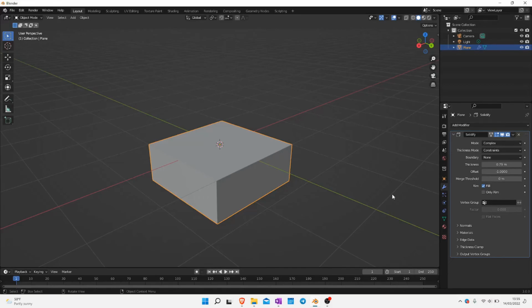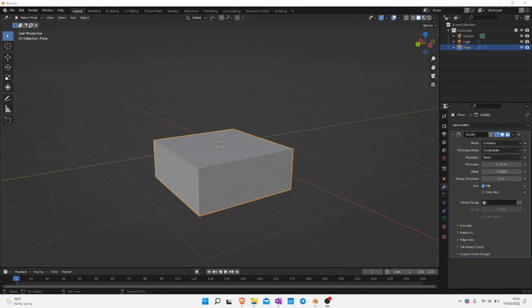The Solidify modifier is definitely one of the simpler modifiers you can use in Blender. It is definitely useful for 3D printing and creating different sorts of scenes, for D&D miniatures or D&D walls, floors, for 3D printing. Animation as well, you can again create walls and doors with it. And again, it's just a simple modifier used to give your object thickness. But just be careful when you are using it, because you might have to do some mesh cleanup when meshes have intersected one another. But there you have it.